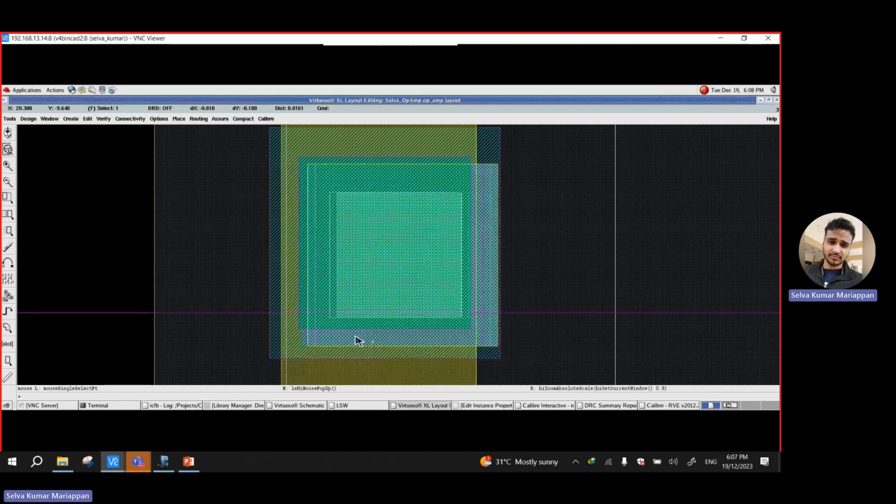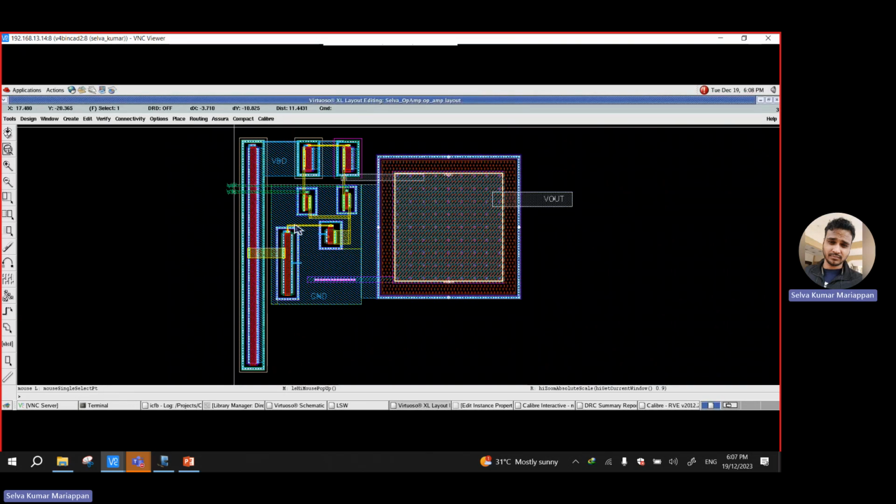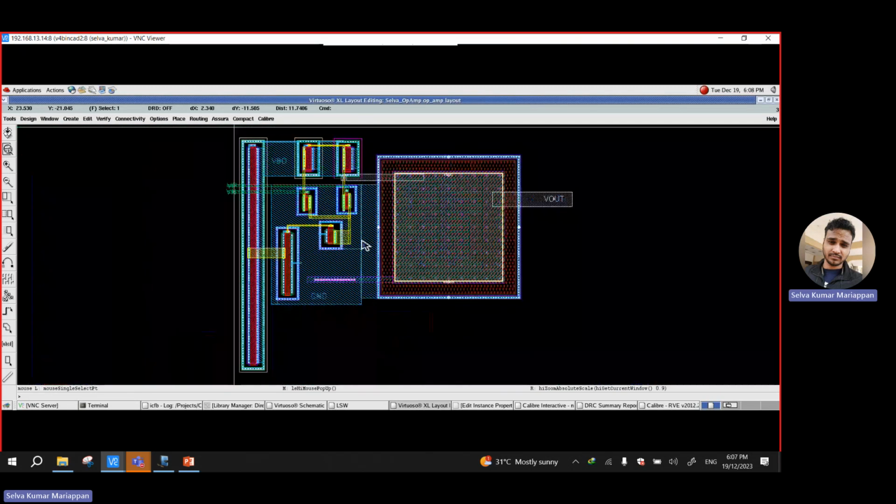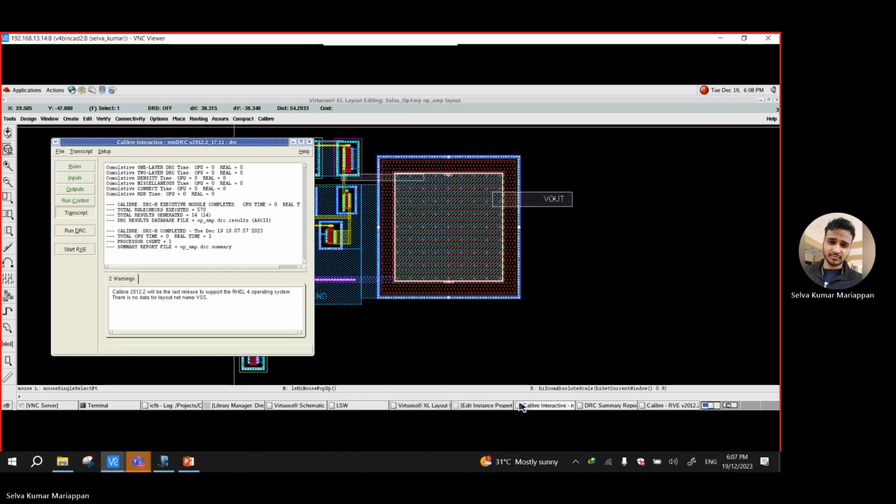See? Okay, so this is for metal 3. It asks us to solve for metal 3. Once you click that, it will zoom into the place and ask you to solve, and you must solve the DRC error. Okay, so that is on DRC.